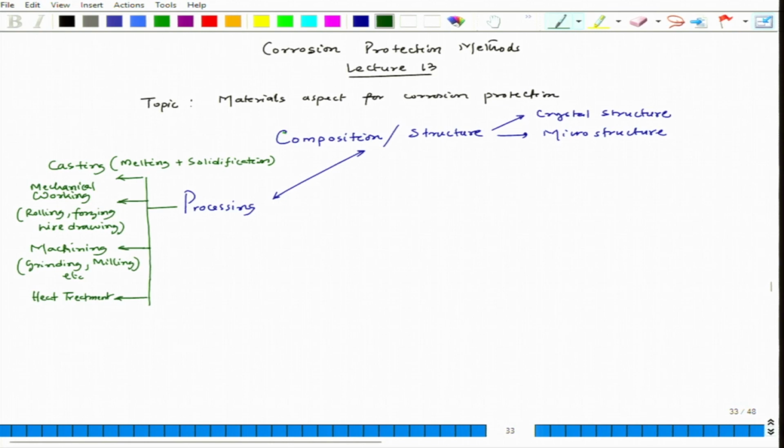If we consider the machining part, let us say this surface is machined. Let us say we have a pearlitic structure. So, let us say that this is the pearlite, which is a lamellar structure of cementite and ferrite. If you do machining like this, with the machining movement like this, the cutting tool, there could be a possibility of alignment of those features along the surface. So, this particular thing can become like this, and it would definitely have an influence on the electrochemical behavior of the surface. That means it can also change the microstructure.